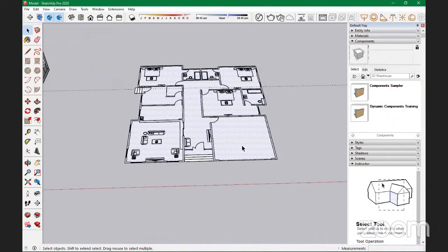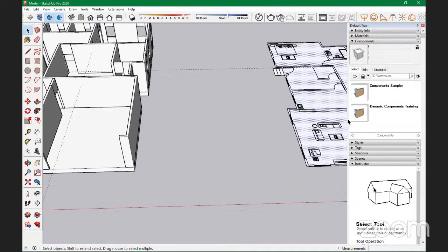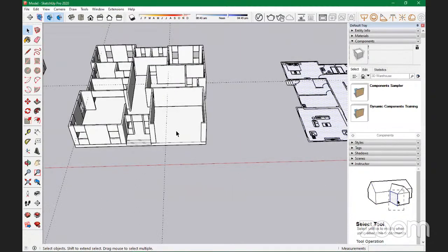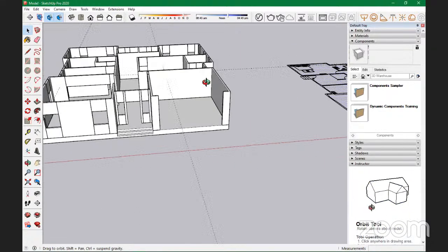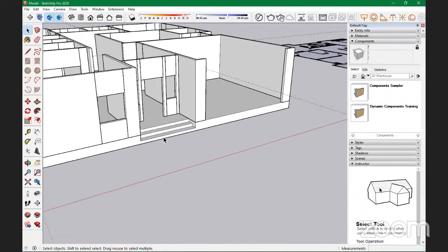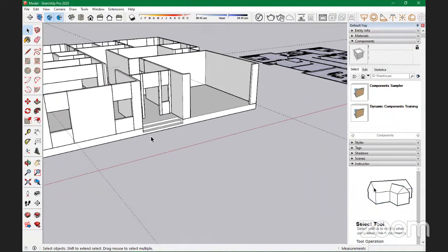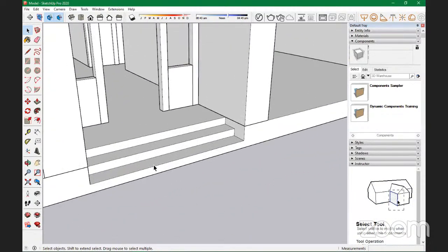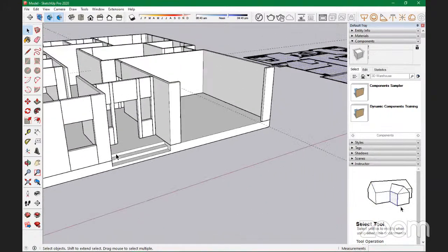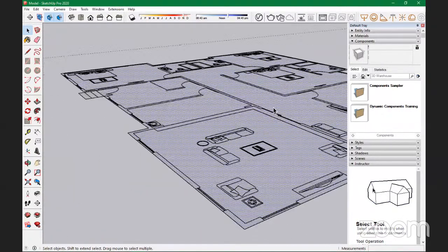For this part, this is the ground floor. Yes, once you climb the stairs, that's where you meet before you enter the building. So that one will be measured by number of stairs. So we have 1, 2, 3, and 3 risers equals 3 times 150, because the height of this riser here is 150 millimeters, and this one is 150 millimeters. This one is 150 millimeters. So the platform here will be 3 times 150.